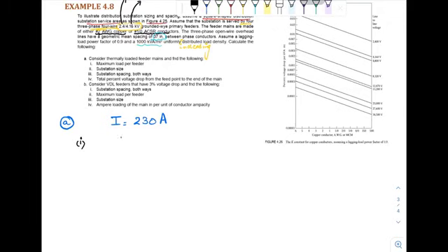As I have told you, the maximum load per feeder is given like this, that is S4, and it will be in kVA. We know that S4 can be easily computed using a simple formula, that is root 3 times V line to line into current. And this is the maximum current carrying capacity of the given conductor type. So we are taking the value of current as the given quantity. The reason is we are using the assumption that the feeders are thermally limited, so we are restricting the upper bound of the current.